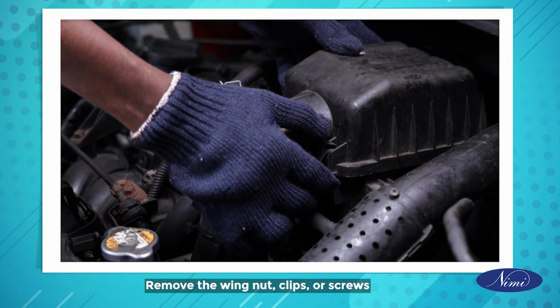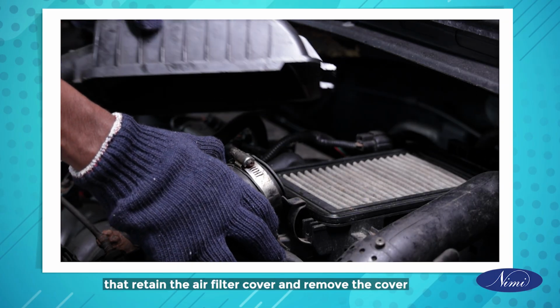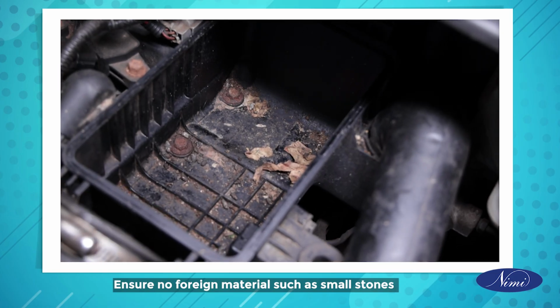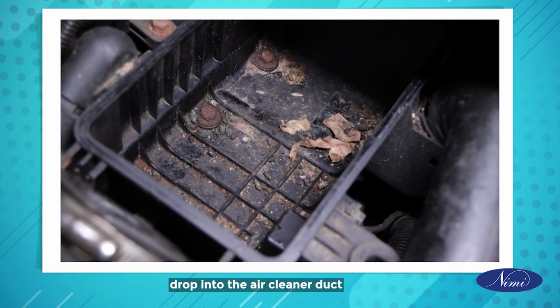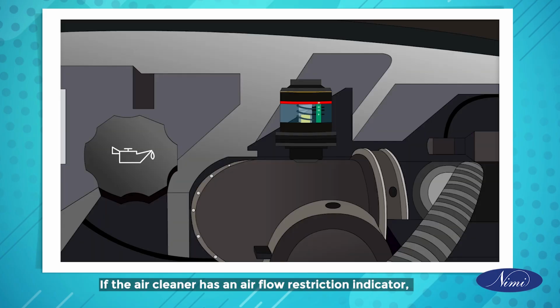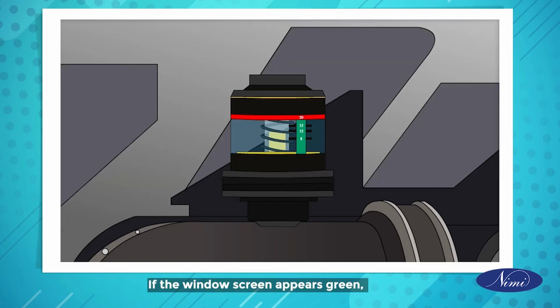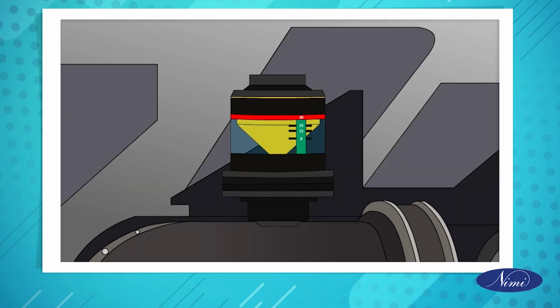Remove the wing nut, clips, or screws that retain the air filter cover and remove the cover. Remove the air filter element from the air cleaner. Ensure no foreign material such as small stones drops into the air cleaner duct. If the air cleaner has an airflow restriction indicator, inspect the color of the indicator window. If the window screen appears green, then the air filter is not restricted. If the window appears a different color, the air filter is restricted.